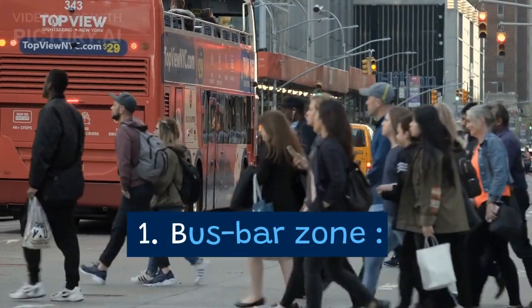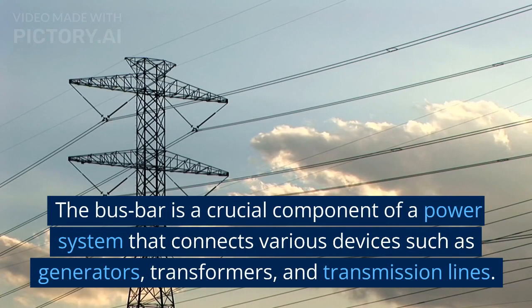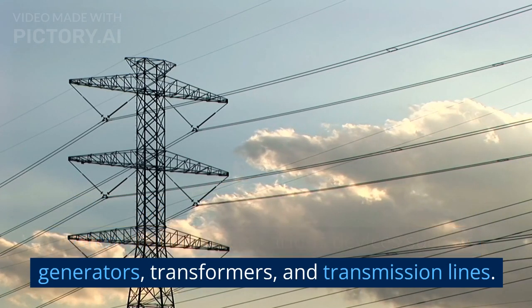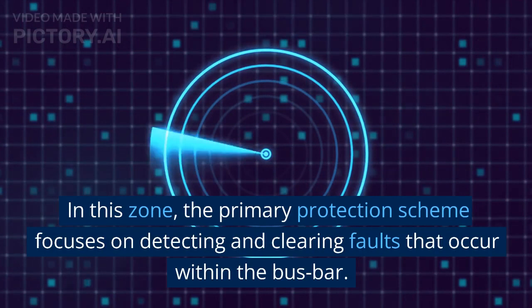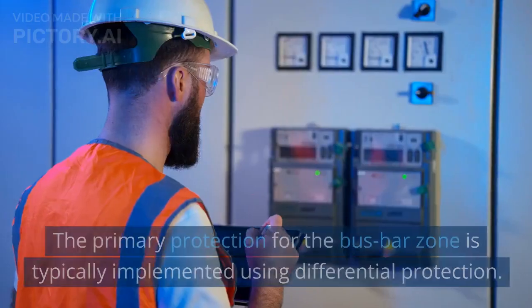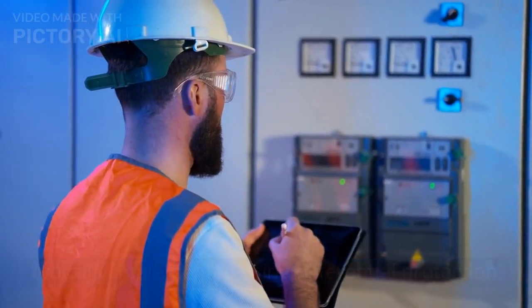Let's begin with the busbar zone. The busbar is a crucial component of a power system that connects various devices such as generators, transformers, and transmission lines. In this zone, the primary protection scheme focuses on detecting and clearing faults that occur within the busbar. The primary protection for the busbar zone is typically implemented using differential protection.